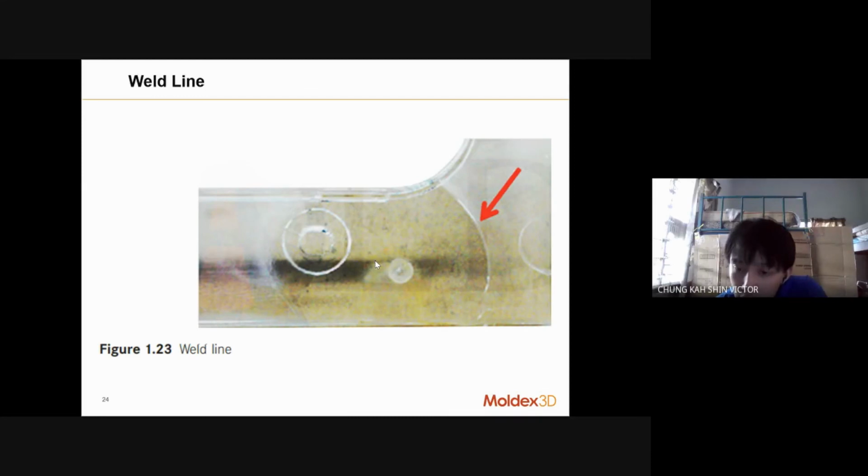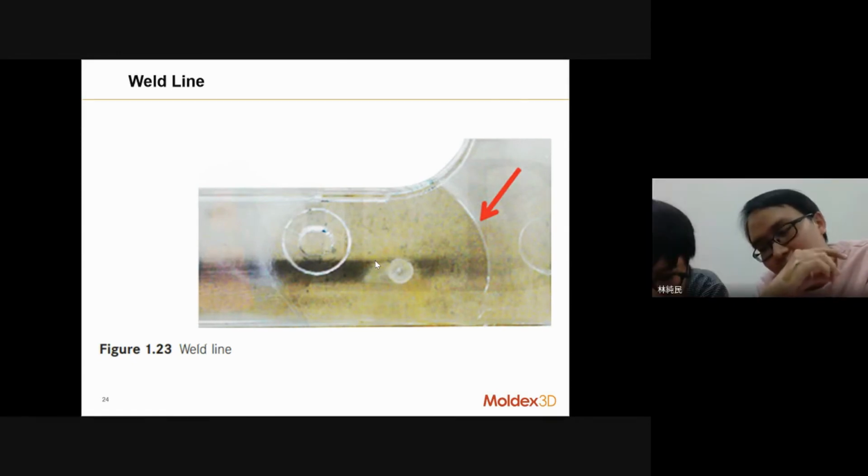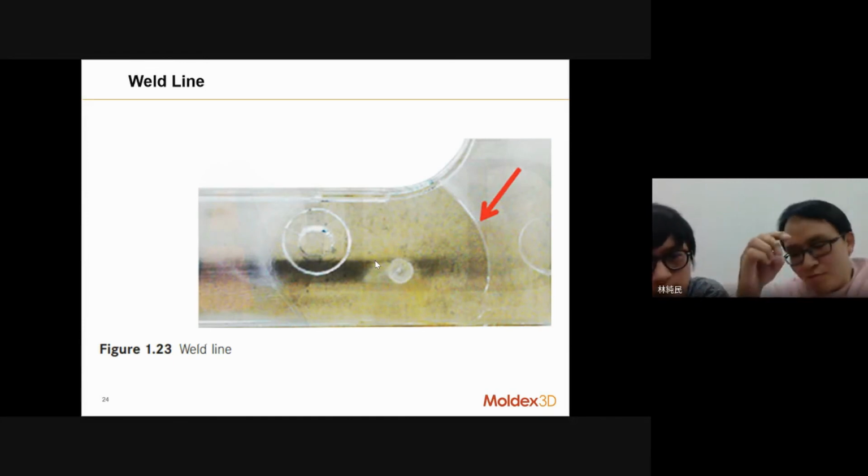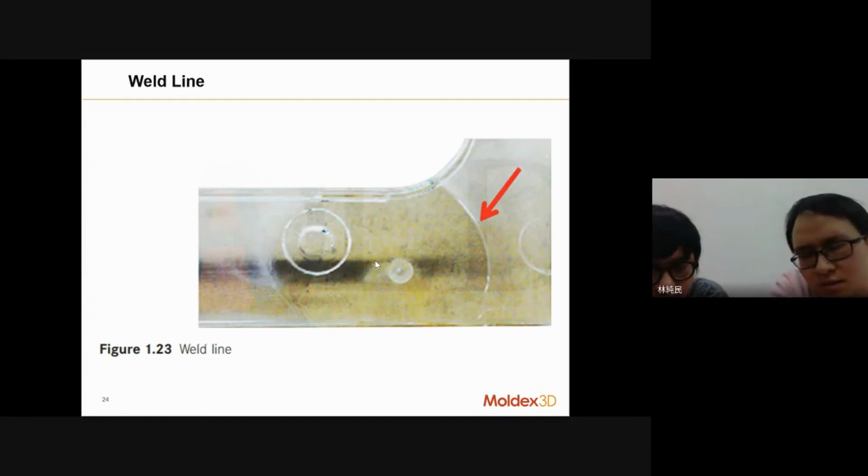Mr. Kai asks, when dealing with the cooling process, can it be simulated accurately when considering active and passive cooling? For the cooling analysis, like we mentioned, accurate or not accurate also comes from the input that we give. Okay, and actually in our cooling solver, we also have the 3D coolant CFD. So it means if you also want to check more detail about the cooling effect to your system while you are running the simulation, you can turn on that 3D cooling CFD.